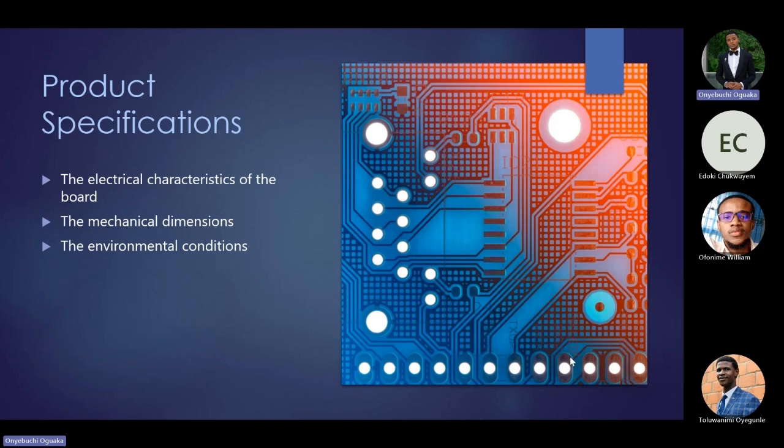So these things can be covered through shielding, that is a conductive coating or metal shielding, enclosing the sensitive components of the PCB, or sections of the PCB where you have antennas or sensitive components that can cause that.